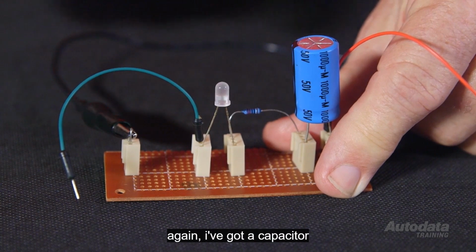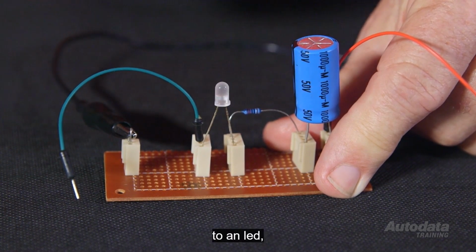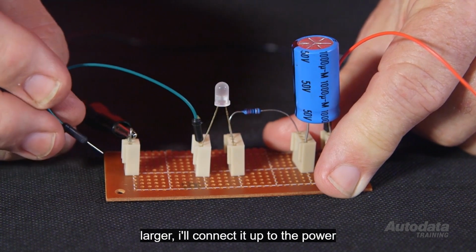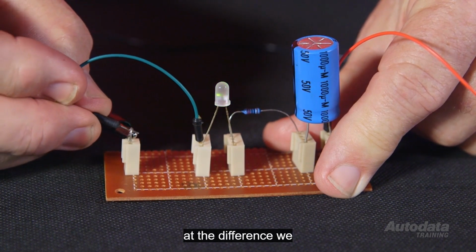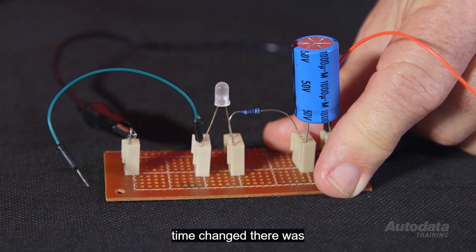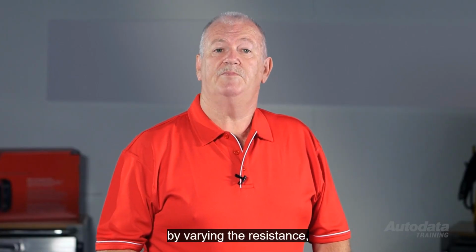The same again. I've got a capacitor in series with a resistor to an LED, but the capacitor is much larger. I'll connect it up to the power and we'll have a look at the difference. We can see the charge time changed. There was a delay.